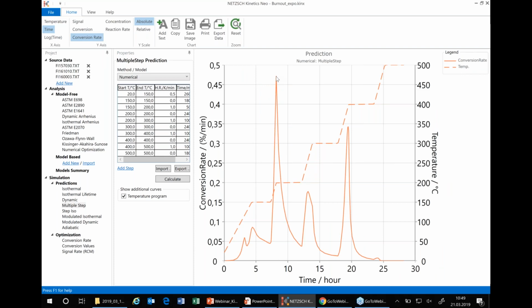Here we have almost 0.5% per minute as the debinding rate. It means that exactly at this point we lose quality. If you would like to make quality better, then we must reduce the heating exactly at this time point and reduce the decomposition rate. How to do this?